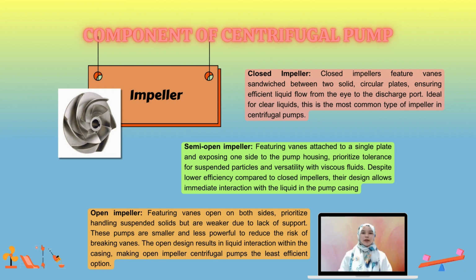Next, the semi-open impeller features vanes attached to a single plate and exposes one side to the pump housing. It prioritizes tolerance for suspended particles and versatility with viscous fluids. Despite lower efficiency compared to closed impellers, their design allows immediate interaction with the liquid in the pump casing.